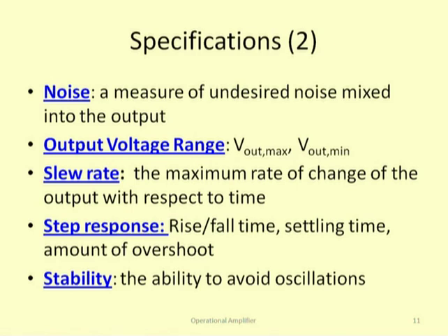The next parameter is the step response. Step response has many parameters. Here 4 parameters are written in the slide. Those four parameters are rise time, fall time, settling time, and amount of overshoot. We'll look at the step response and understand the meaning of these 4 parameters.